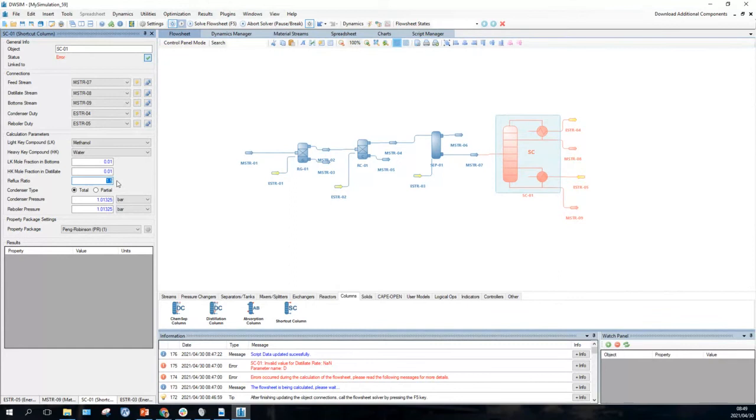Reflux ratio, I think I chose 1. Let me look on this thing. Reboil at 1 bar. Forgot to put in that. All right, so then I expect you would have used 1.5 as the default. Damn. So let me rather use 1, which I'm pretty sure I used when I did this, because we were looking at different numbers further on, and then at least those numbers are going to work out. Sorry, that didn't work out for you. I suppose they would have worked out, but yeah.